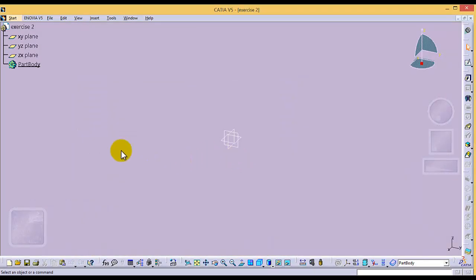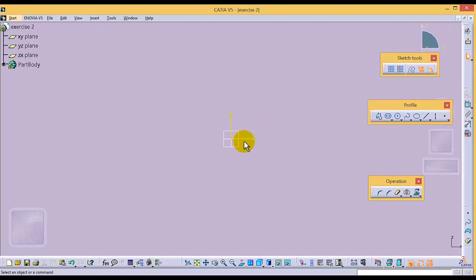It's okay. We are going to start the sketch on the YZ plane. It's our front plane, and then click on sketch. After that, you can do it in different ways. So I am first going to draw a circle at the origin where the coordinates are 0 0, and then I am going to draw two lines touching this circle. Just draw it randomly.